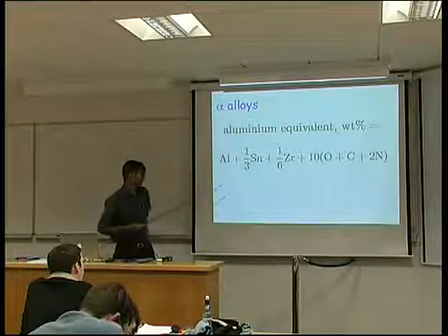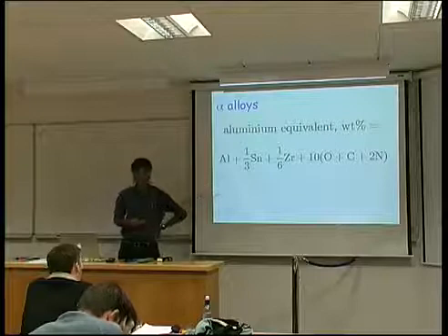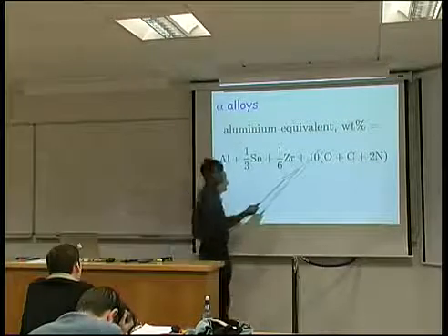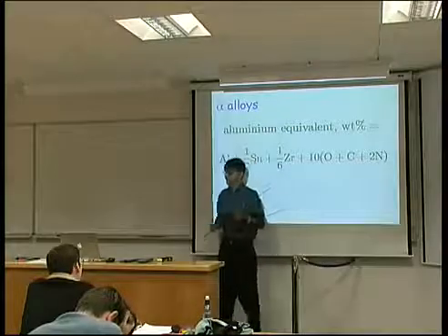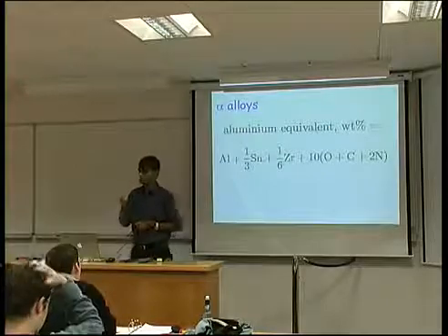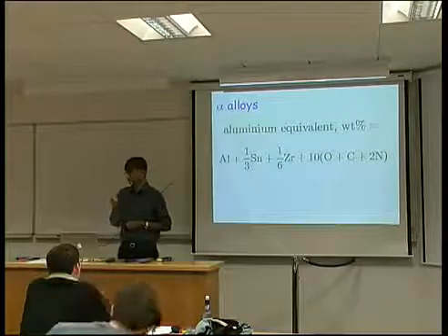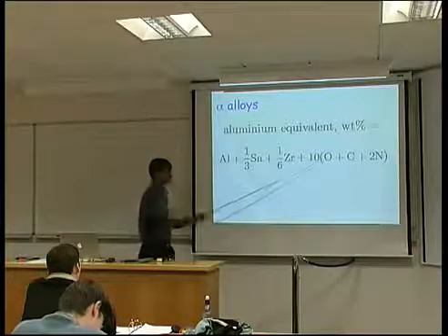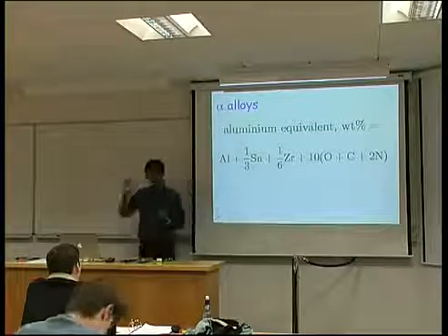One of the problems with aircraft alloys is that if you accidentally introduce oxygen into the alloy, you will end up with very hard alpha particles, which cause major problems with respect to fatigue failure. So for aircraft alloys, you want to keep the oxygen concentration down as low as possible.